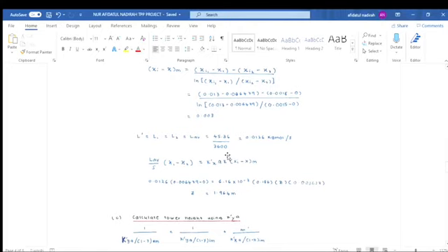So after we know all the values, L average is equal to 0.0126, x1 minus x2 is equal to 0.006479 minus 0, K prime x is equal to 6.16 times 10 to the power of negative 2, a is 0.186, and xi minus x is equal to 0.003627. The only unknown here is z, which is the height.